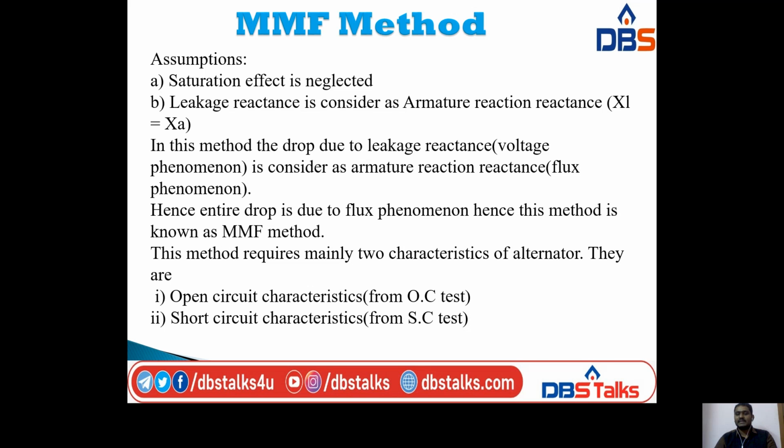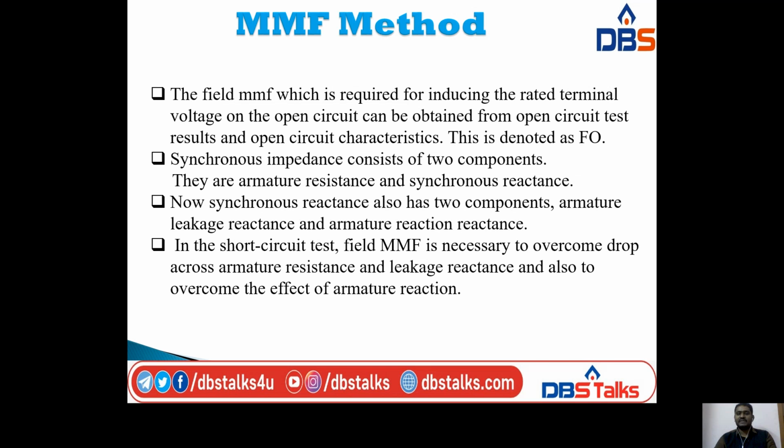This method requires mainly two characteristics of the alternator. They are the open circuit characteristics, obtained from the open circuit test, and secondly the short circuit characteristics, obtained from the short circuit test. The field MMF required for inducing the rated terminal voltage on open circuit can be obtained from the open circuit test results and open circuit characteristics. This is denoted as F naught, F suffix 0.